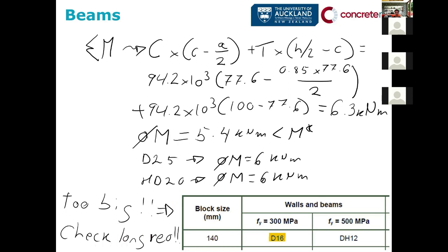We just need to change the longitudinal reinforcement. We need to change the size of the beam, and use a 390 block instead of a 190 block. And that's all. As simple as that. It's just a beam with a moment on top coming from the UDL. Simple.